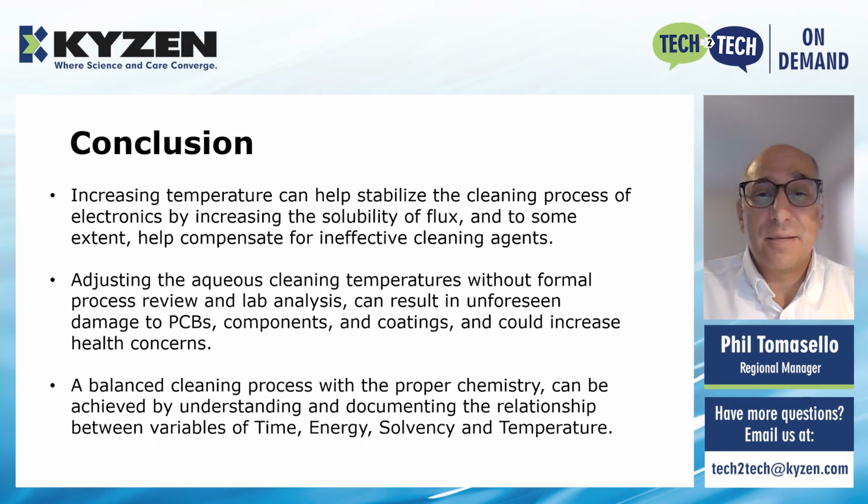Trying to adjust the cleaning temps without having a formal process review or lab analysis certainly can result in some unforeseen damage to those PCBs, to the coatings, to the components, possibly increase some health concerns. So you really need a balanced cleaning process using the proper chemistry and understanding and documenting the relationship between those key variables, right, of time, energy, solvency, and temperature.